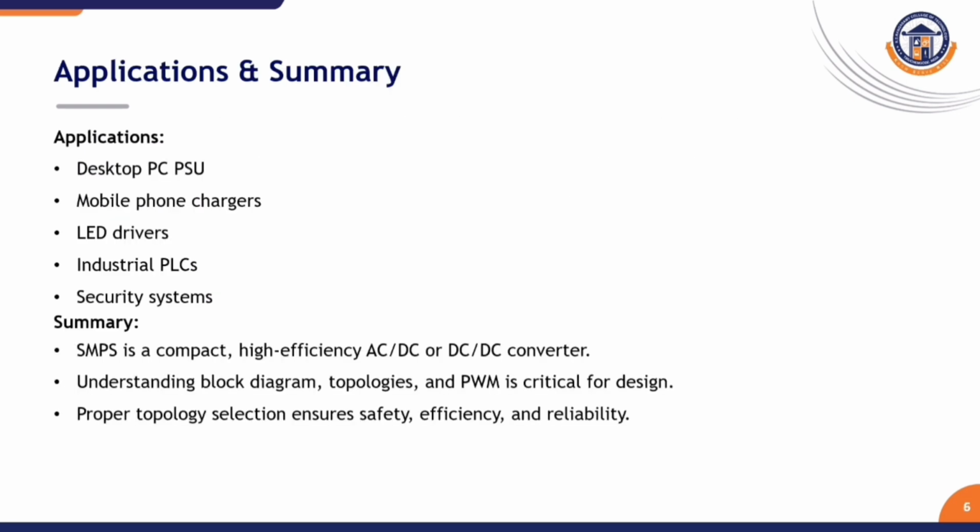The SMPS is used in desktop computers, mobile phone chargers, LED drivers, industrial programmable logic controllers, simply we call this industrial PLCs, and security systems. To summarize, SMPS provides high efficiency, compact size and reliable power conversion, which makes it ideal for modern electronics systems.